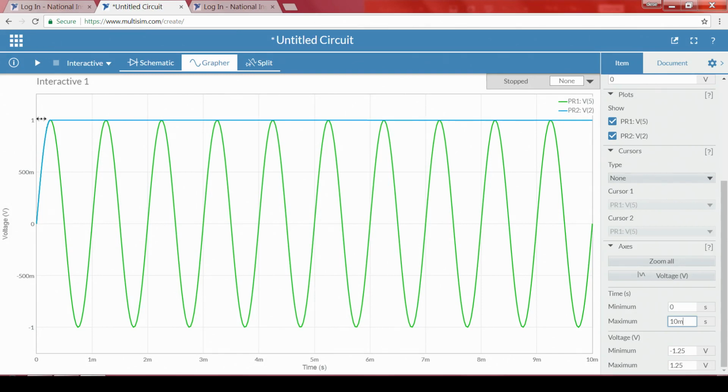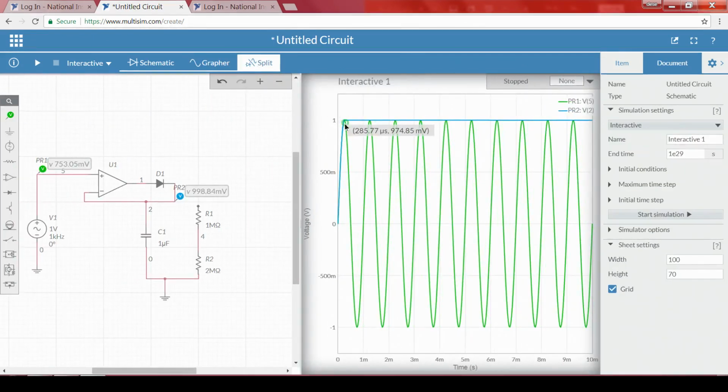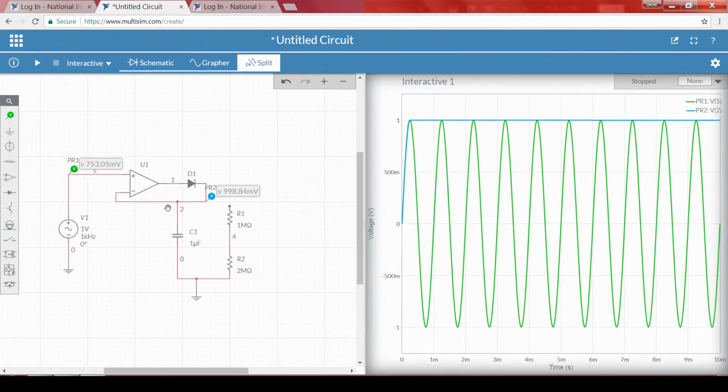What if I change my input? If the input voltage is 2 volts, the capacitor slowly starts charging to the 2 volts value. The whole idea of this circuit is to find out the peak value, and whether the purpose is solved or not, let me check.